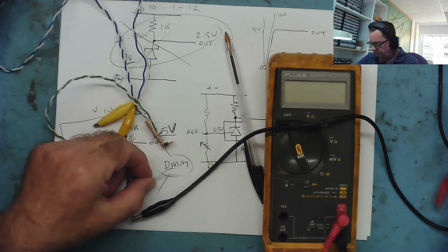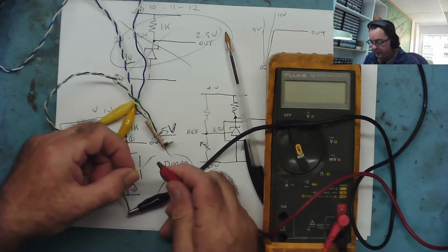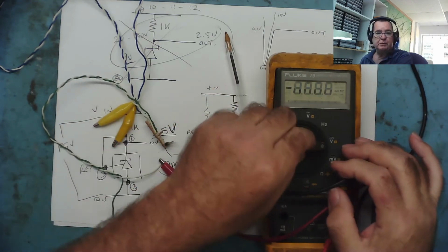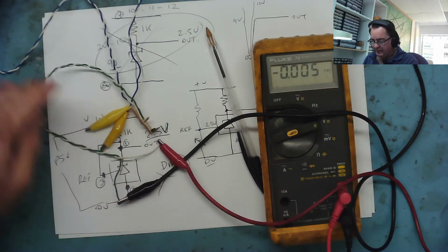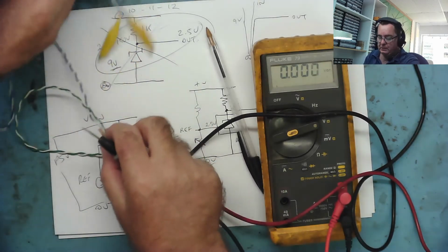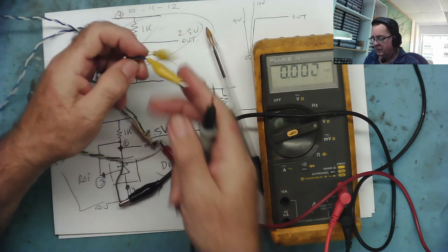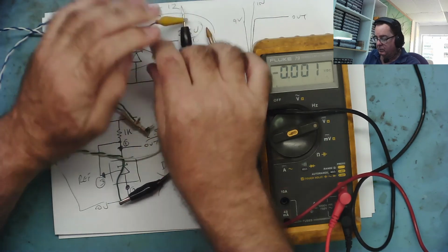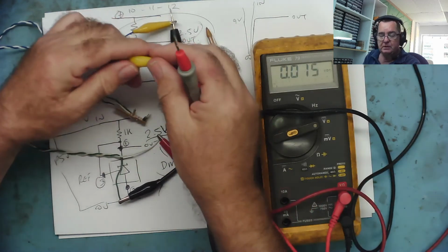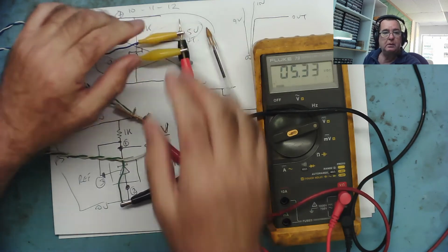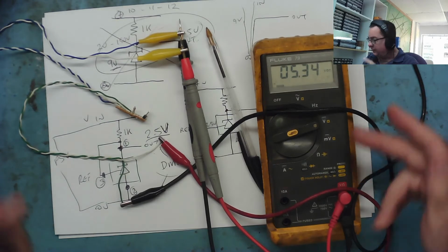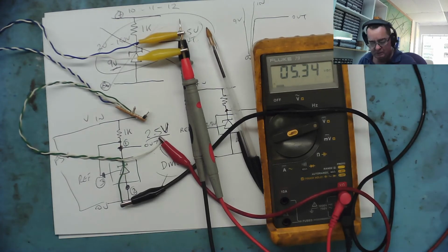Okay. So this is the power coming in, 5 volts. Put the meter onto voltage range, and then this blue and white goes to your meter. The blue one is ground, negative, and the white one is the red, the positive. And there we have 5 volts. That's what we expect. 5.3, I told you it was set to 5.3 on the power supply.